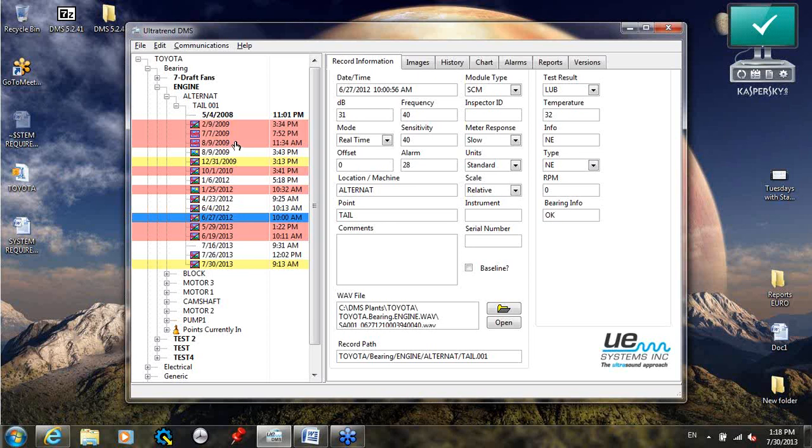Anything that pops up as red is basically a high-level alarm. And dealing with bearings, anything that pops up as a red flag usually tells us that we have beginning stages of physical damage that we can actually see with our own eyes. So you can see the flaking, the spalling, even sometimes flat spots on the bearing itself. So it gives you indications of what's actually happening inside that bearing without really tearing anything apart. So it's very non-destructive using UltraProbes for this application.